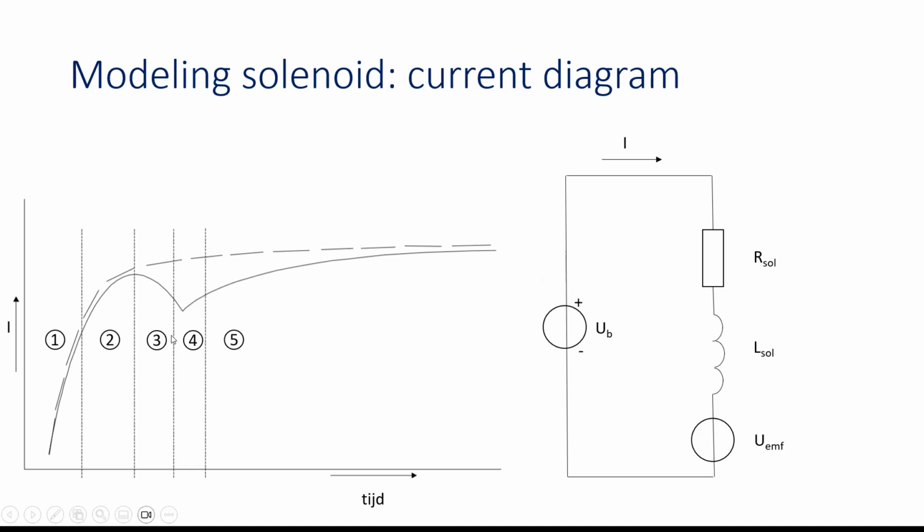When you, for instance, measure that current through an inductive probe and an oscilloscope, and you measure this point in time, you know exactly at which point in time the plunger is at its maximum inner position.